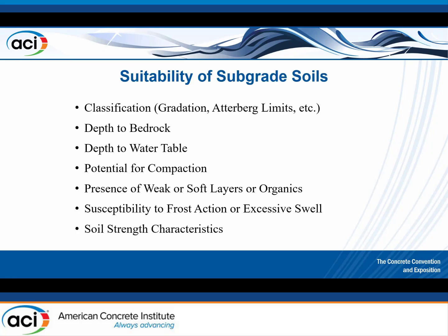So when we talk about the soils, we have to come to a common agreement about what's important. And we typically do that through a geotechnical engineering report. What that geotech report is trying to do is tell us about the suitability of that soil for the environmental conditions and for the traffic loading conditions. Those two things become very critical in determining how thick our pavement needs to be or how it's going to perform. So we do look at the classification of the materials, the native soil that's there. How deep is the bedrock? That's also an important factor. Where's our water table, or how much can it vary from one season to another?